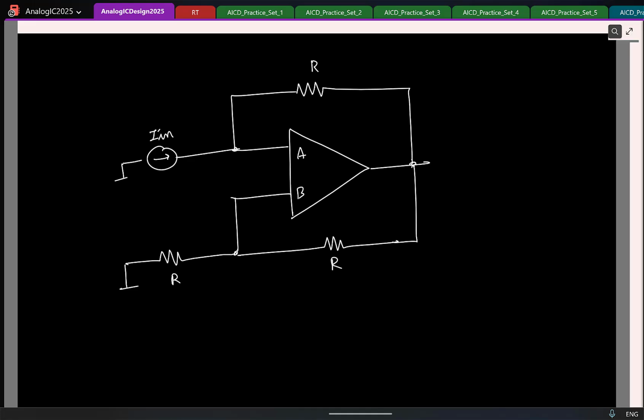You apply voltage at VA and VB. Remember, it is known that now we have both positive and negative feedback. Our goal is to make sure that we assume an appropriate sign so that the DC negative feedback dominates, right? So again, remember, for checking the signs, we can assume the inputs to be 0. So I'll assume the current to be 0. So this is open circuit basically.